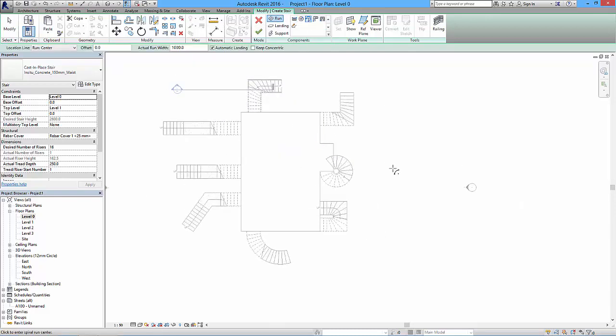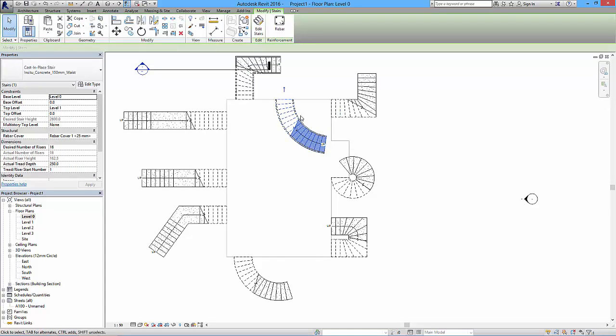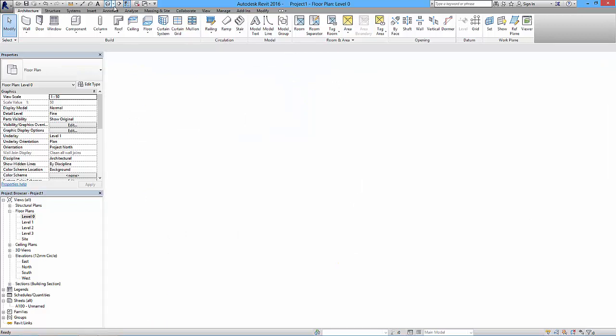So let's do this from this point. So 0 to 1. So let's pick a corner point, and now we spin this out whichever way you want. So maybe we'll have it like so, and then we start creating our risers like so. Create it, and then what we'll have to do, because this is underneath coming up, which is a bit ridiculous, we might then want to select this and just mirror it based on a pick line. So we pick that line, and it's going to pop it in the right way around. Okay, so more than one way to finish these things off.